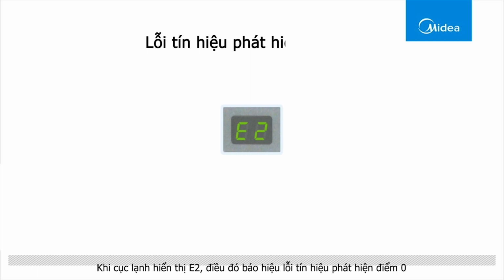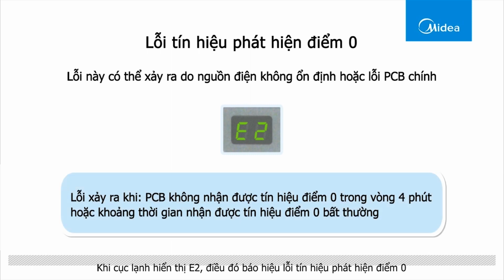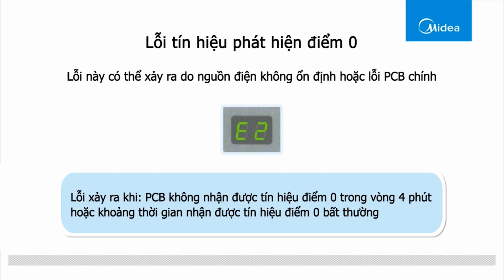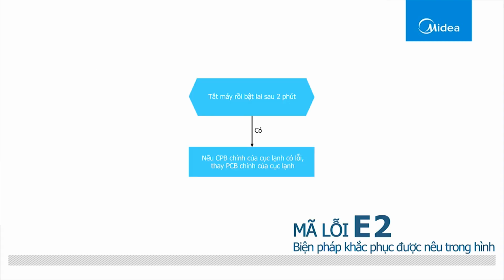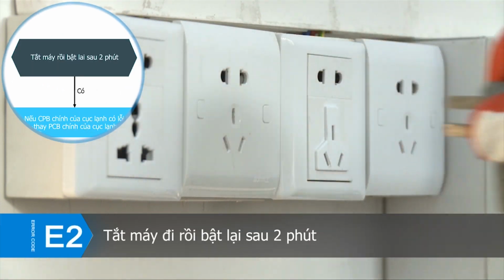When the indoor unit displays E2, that indicates zero crossing signal detection error. This failure could be caused by erratic power supply or main PCB error. Malfunction decision conditions. When PCB does not receive zero crossing signal feedback for 4 minutes, or the zero crossing signal time internal is abnormal. Shut the power off, then turn the unit on 2 minutes later.